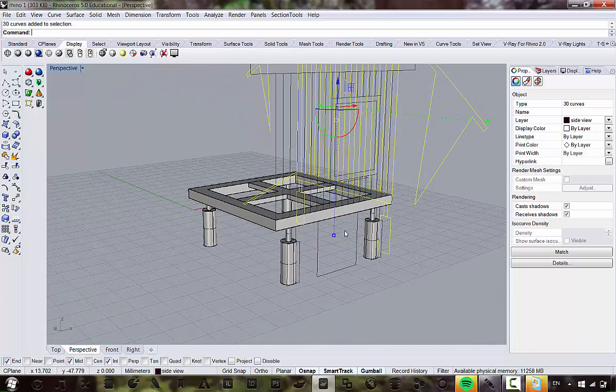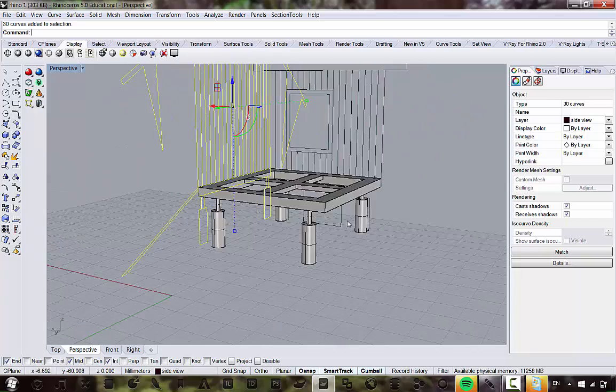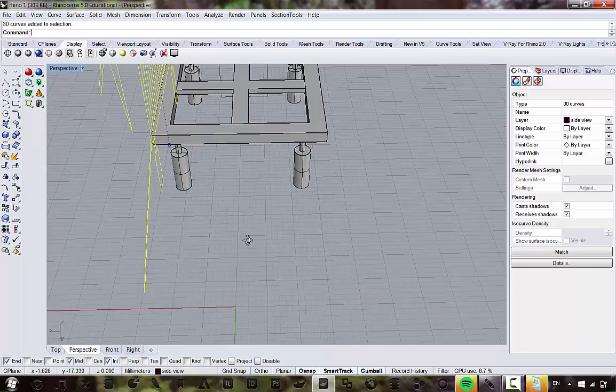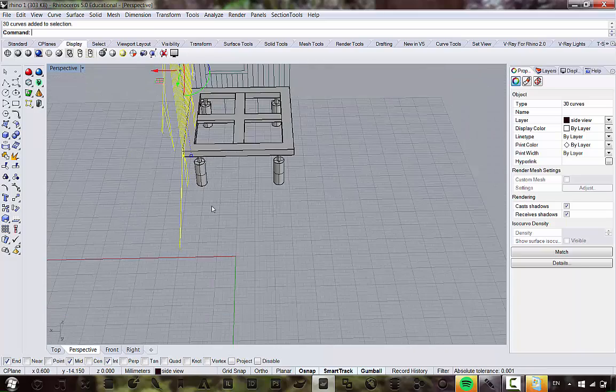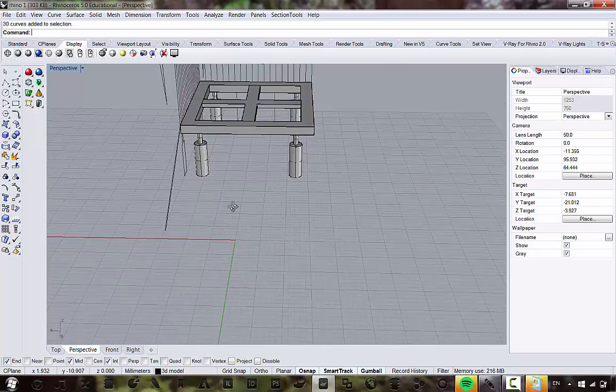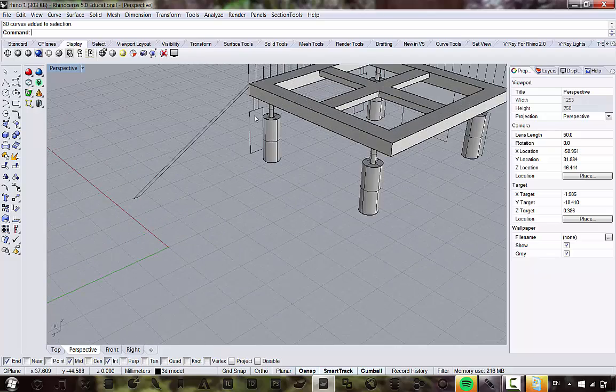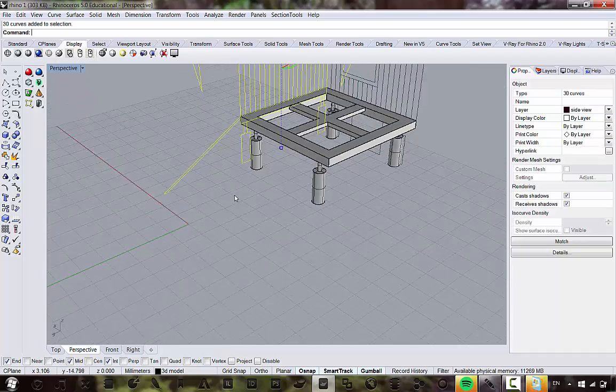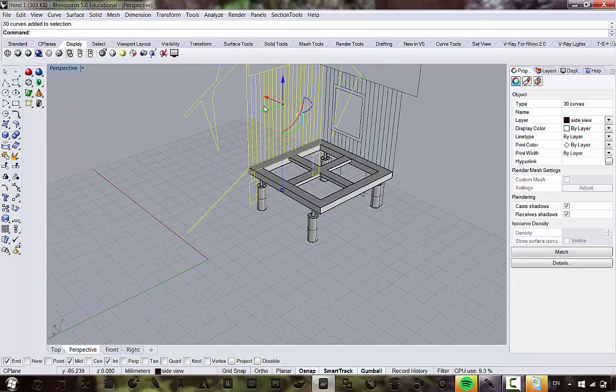So with this ramp, we don't have any detail here, but we'll add some detail. Essentially what we're going to learn to do, I guess, is add maybe like a diamond kind of pattern to it, sort of add something. So with this, we're going to start by just extruding this curve. So I'm actually going to ungroup this here so we can grab that curve. So I'm going to hit Control-Shift-G.